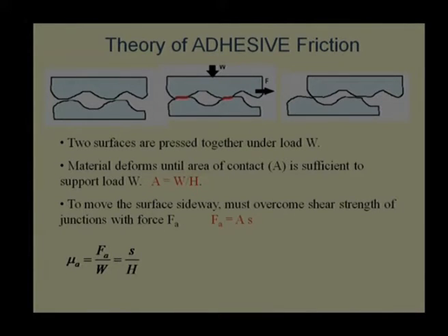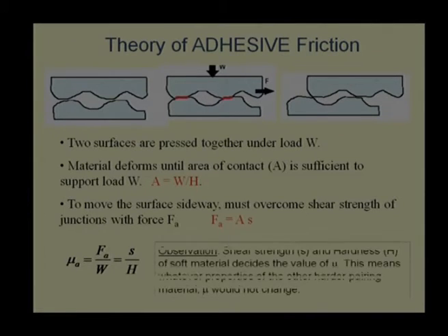in this case. Only point of variation will be that quite possibly S for the softer material is higher and the interface has a lesser one, in that case S will be slightly lesser. However, for time being we are assuming S is a material property of the softer material, H is the hardness of the softer material. What is interesting in the observation from this? Say that shear strength and hardness are related to the material.